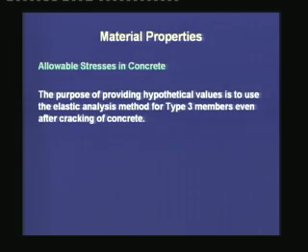This is an interesting point to observe. After the concrete cracks, the elastic analysis cannot be used in its exact sense, but the code allows us to use the elastic analysis for the service loads, so that the analysis procedure is simple, and it specifies some hypothetical maximum tensile stresses in the members, which ensures that the cracking is not extensive in the type 3 members and the crack width will be limited.